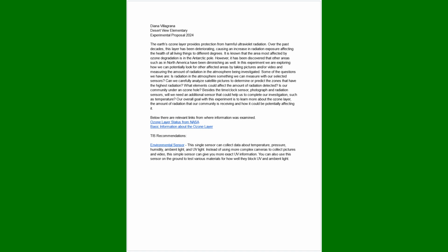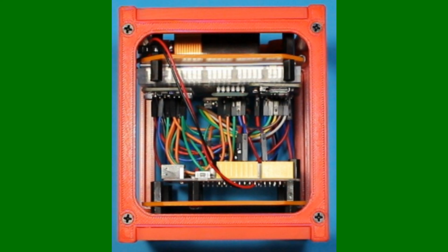The way that we did the CubeSats in the workshop, you might want to reconfigure how it's facing, because in the workshop, if you were to just put the sensor directly into the CubeSat as it is, you probably wouldn't get as much direct sunlight on it. So that's something to keep in mind. If you need help figuring that out, I'm always available. I can give you some ideas.